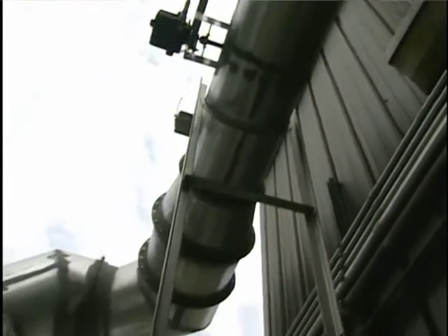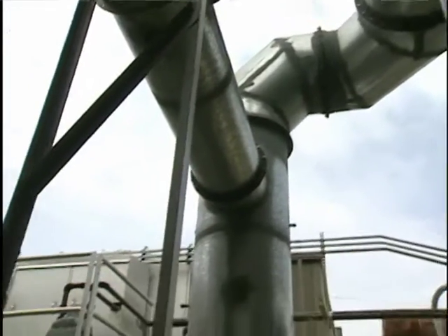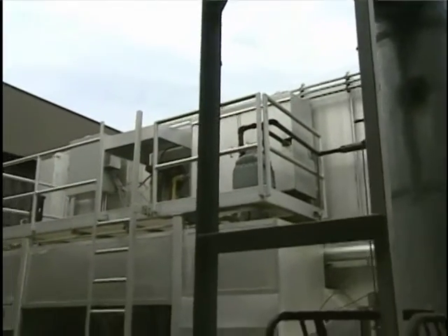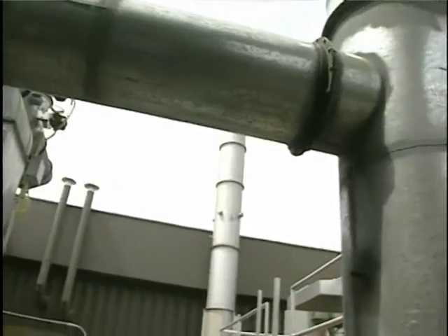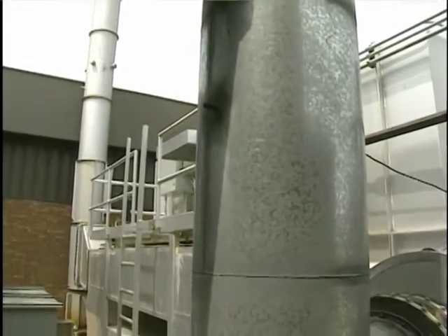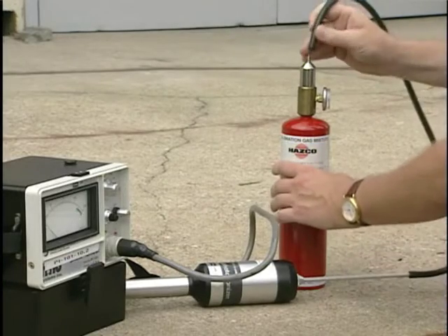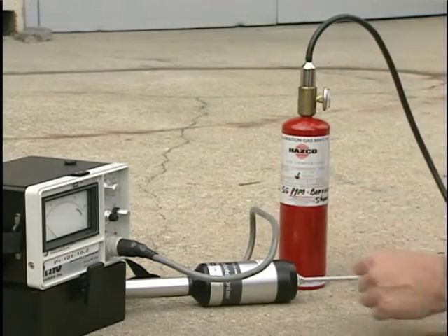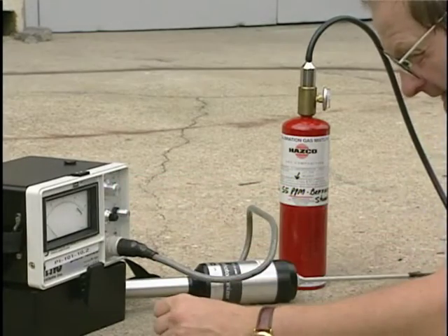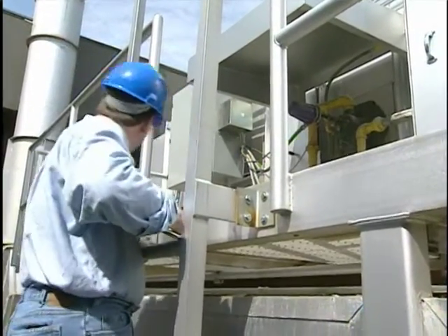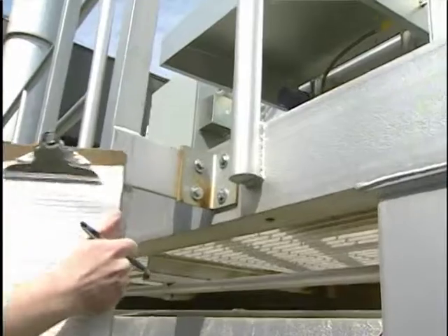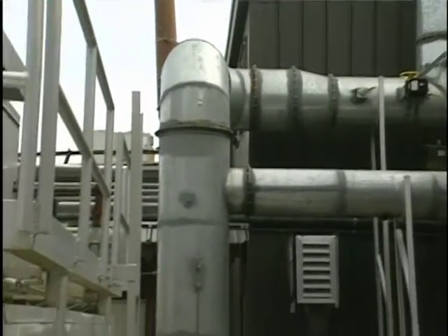Both the inlet and the outlet gas temperatures are used to evaluate the performance of a catalytic oxidizer, since the temperature difference is directly related to the amount of organic vapor being destroyed. Decreases in the temperature difference across the catalyst may occur because there is less organic vapor in the inlet gas stream. This condition could be evaluated using a portable analyzer or a permanently installed lower explosive limit detector if one is available. Decreases in the temperature difference will also occur if there has been a loss of catalyst activity, since less of the organic vapor would be destroyed.